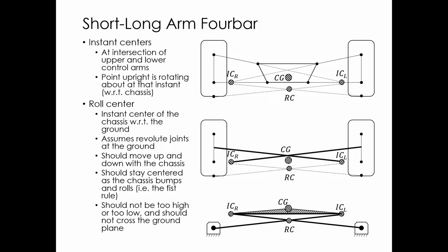So if you can position your suspension instant centers to where when the vehicle goes around a turn, the tires tip into the turn a little bit, you can make the car a little bit faster. And certainly if you can prevent them from leaning out of the turn, it's going to help a lot. It might be a few percent, 5-10% more, but that's pretty significant at the end of the day.